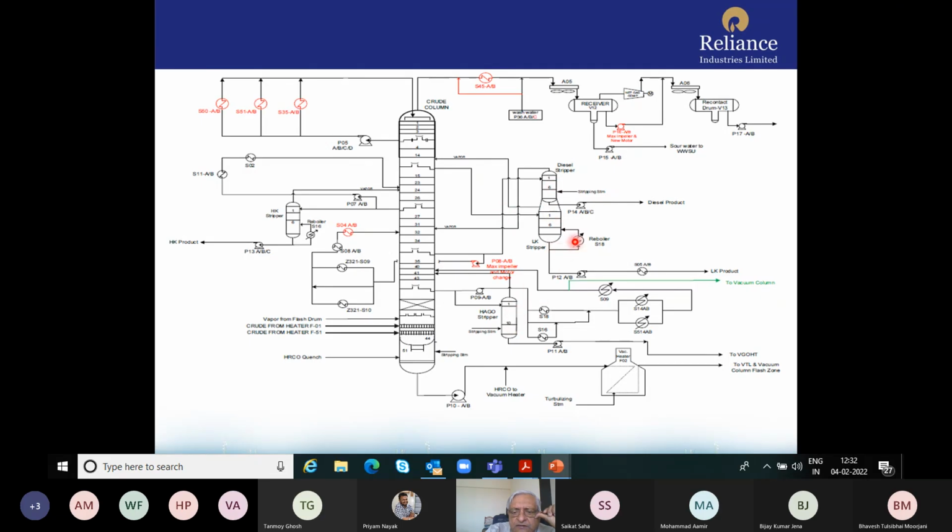And here you can see that there is no steam stripping. There is a stripping steam here, but there is no stripping steam here. This is actually a reboiler, because this is the jet fuel that we are producing there. And then you have this top section, where in this case, what these people have done is that they are trying to recover that heat also into the crude.